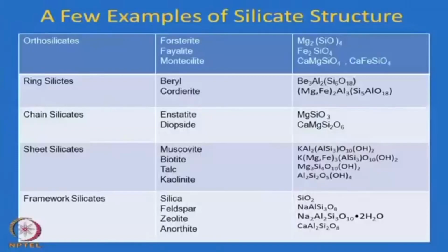So, aluminium has a kind of dual character, it can go to the octahedral site, and it can also go to the tetrahedral site, and that is one of the important features of many of the silicate structures. So, here that is what is happening. So, that is the cordierite structure. Now, cordierite is once again a very important compound in the family of ceramics.